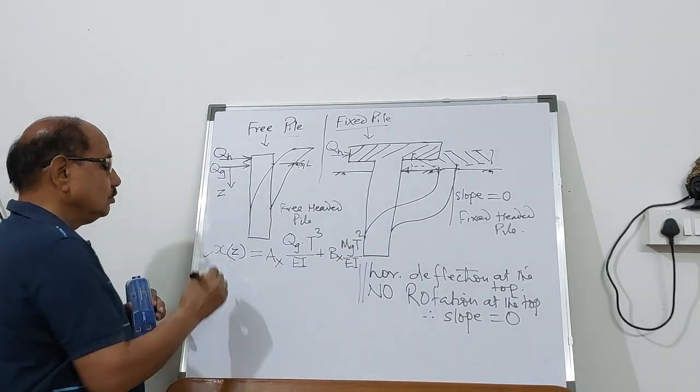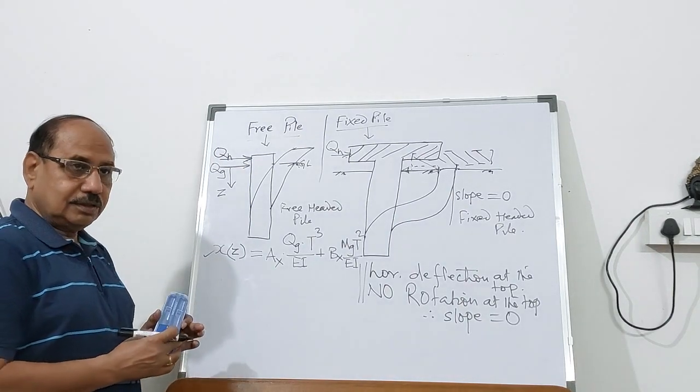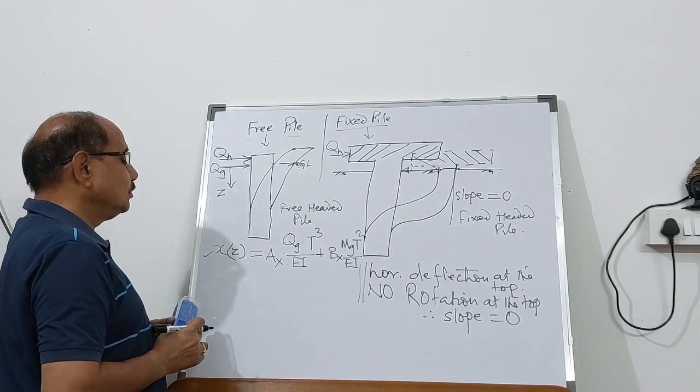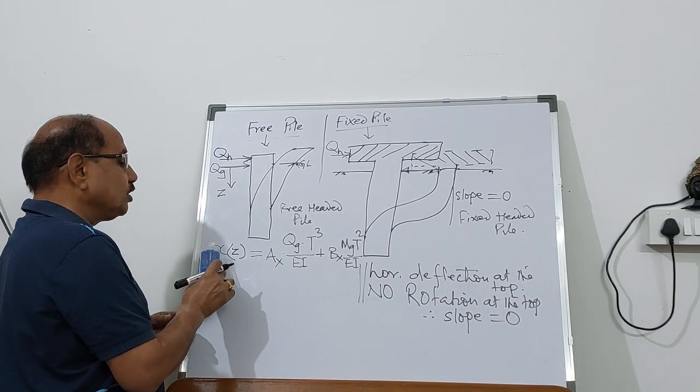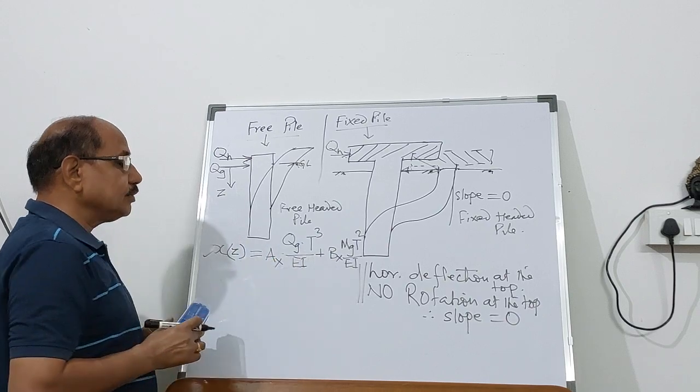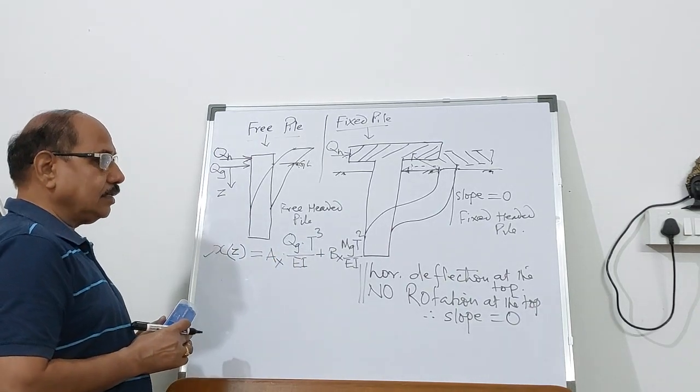This equation you have used in the previous video, and you have found out the deflection, or if the permissible deflection is known to you, you can find out the lateral load carrying capacity of a free-headed pile.